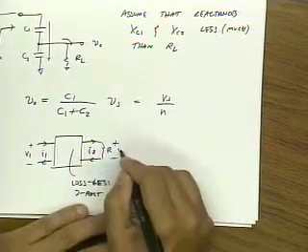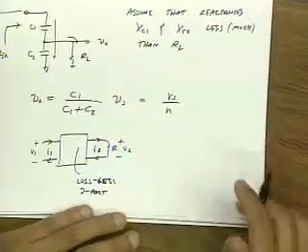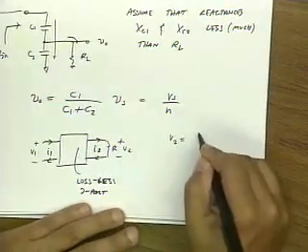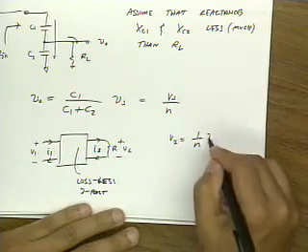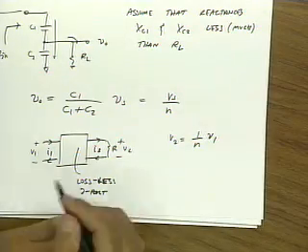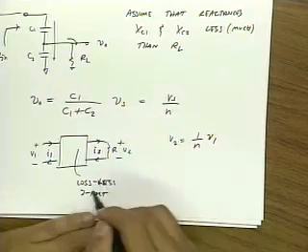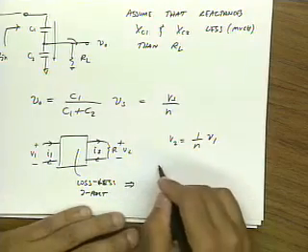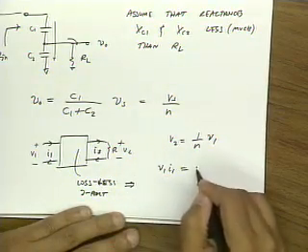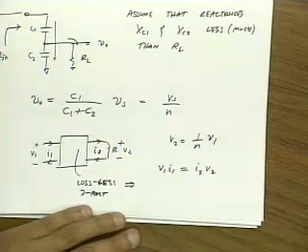And this is V1 and this is V2, I1, I2. And let me assume that V2 is 1 over N times V1, right? This could be a transformer, for instance. Well, because it's lossless, that implies that V1 I1 has to equal V2 I2, right?